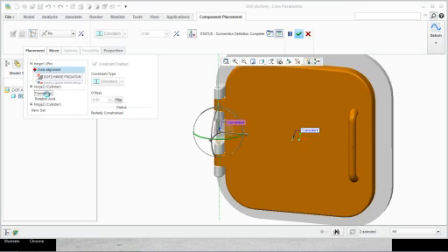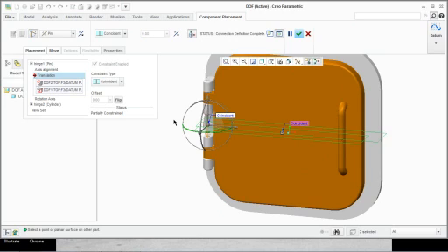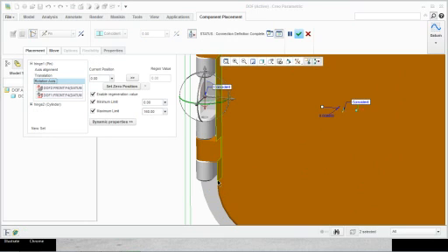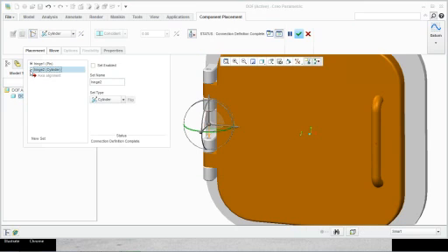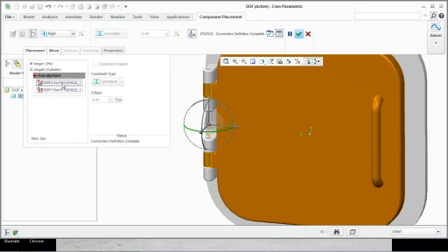Okay. Say we use the pin joint to create this. Now that should be good enough because this is the software. Mathematically that's good enough. In real life you might need a hinge or a cylinder at the top too. See what I'm saying? Even at the top. But notice this constraint is disabled.